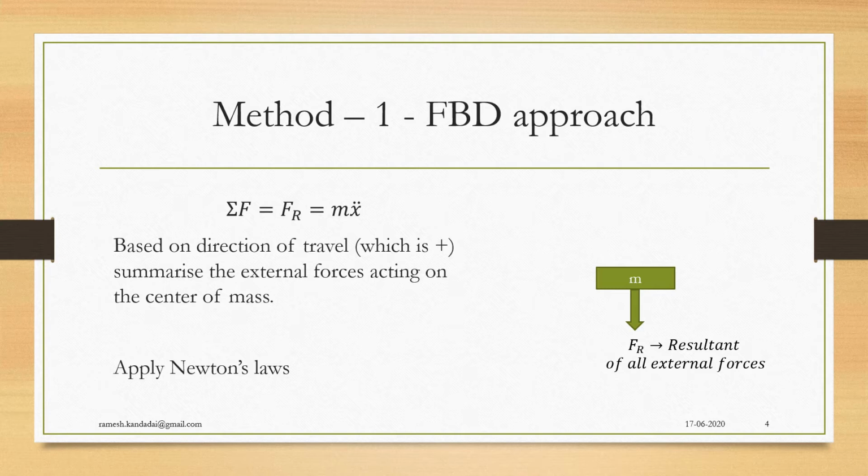If you can derive the equations of motion, you can analyze the system of body or bodies so that you can tell about what they will do subject to a certain input. So the first method is to do a free body diagram. Why a free body diagram? Because with a free body diagram, you establish a balance of forces, externally applied forces. By taking the externally applied forces, you'll be able to find a resultant and its direction.